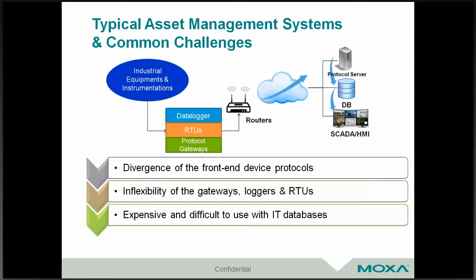The challenge that we see in remote data acquisition systems like this can be summarized in threefold. The first one is how do you convert the front-end device protocols? The second is that since those data loggers, RTUs and PLCs were created decades ago, they do not have the programmability and flexibility allowing you to do some data tweaks in order to feed the data seamlessly into a database.